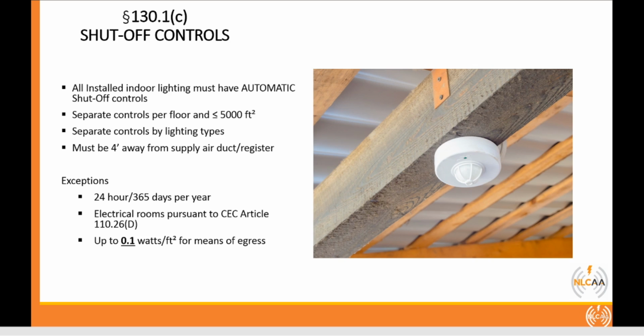Now, code will dictate in some areas where you must use occupant sensing controls as a means to do your automatic shut off. You can't just use time clock or building automation in those areas. But we can cover that in the next slide.